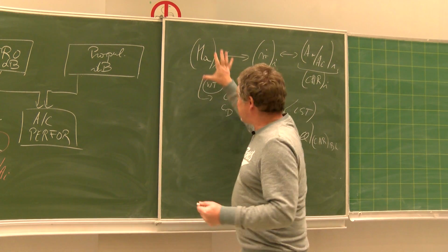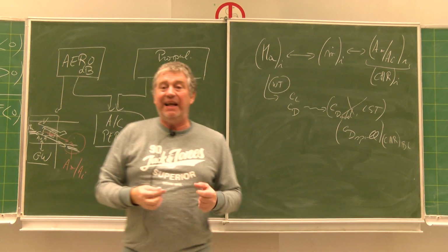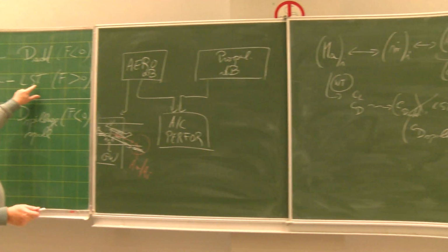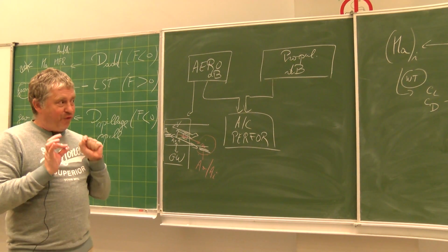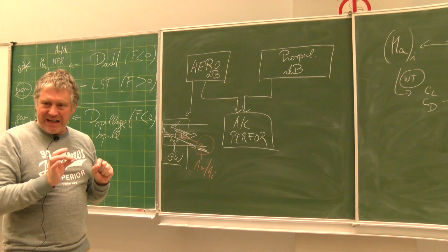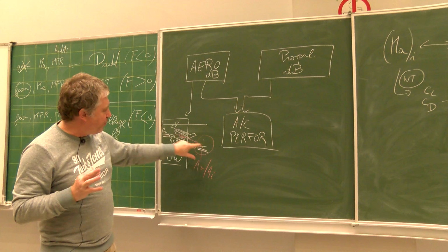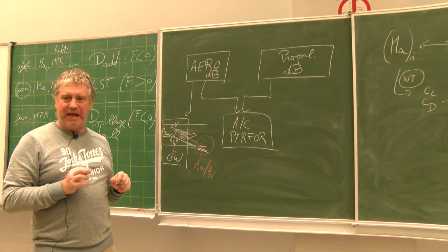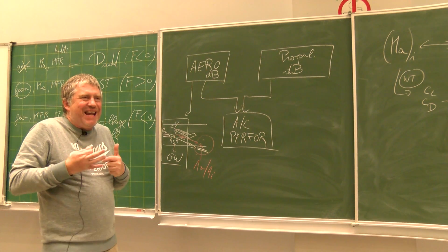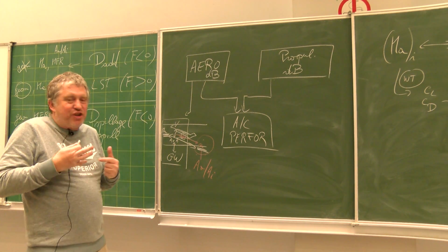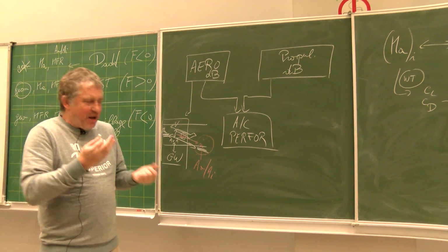So in these tests that they are doing, measuring on the aerodynamic balance, it's including this and this. So it's including the sum of the other two, but only for the baseline, the reference that they are taking corresponding for each Mach number with m dot and AA divided by AI. So it's not enough. What they have must be, let's say, added. They must correct the parameters that they have with something else.